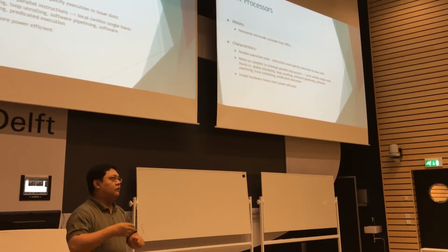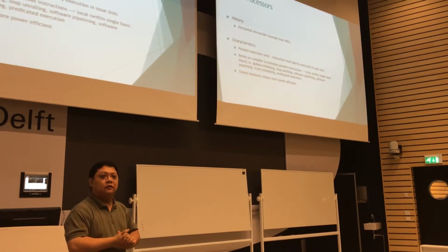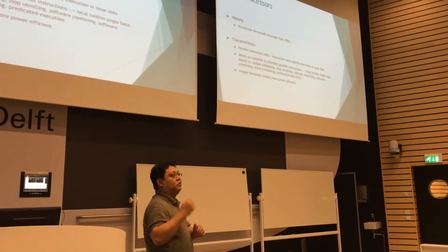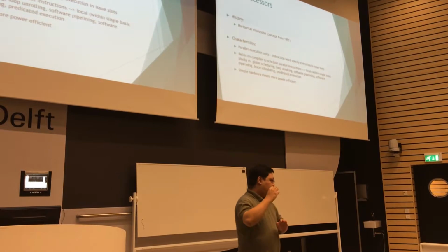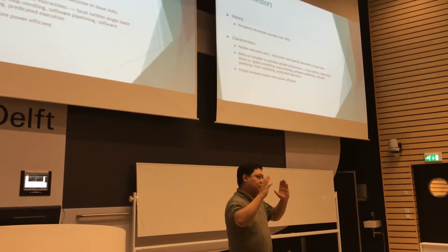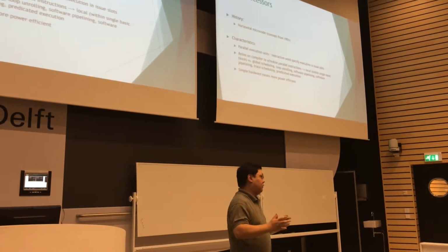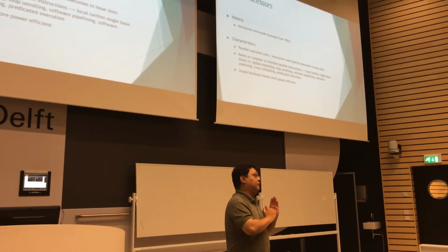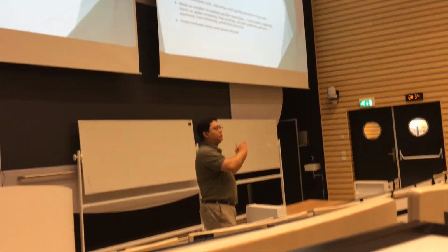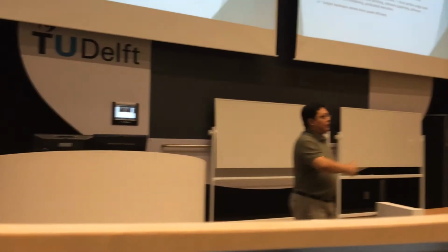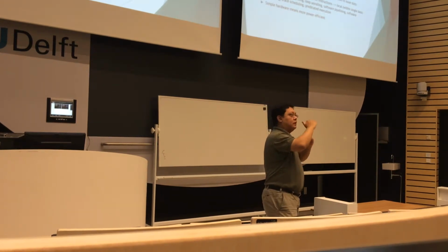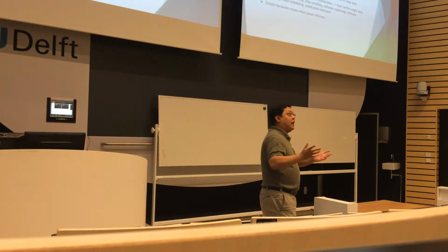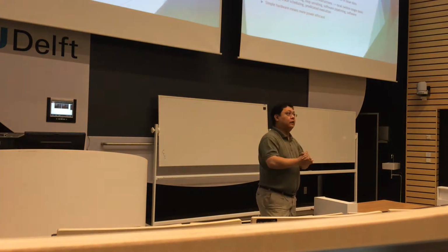Yeah, so it contains a sequence of operations that emulates the functionality that I would like to do, right? Now, that emulation is precisely what microcode is. You cut or subdivide your big operation that you cannot implement in a piece of hardware these days into smaller pieces, and all of these pieces you can implement. These operations are called micro operations or micro instructions, and the sequence of operations is called microcode. That means when I would like to implement a certain instruction that you don't have, you microcode it, and then you can have the same operation.